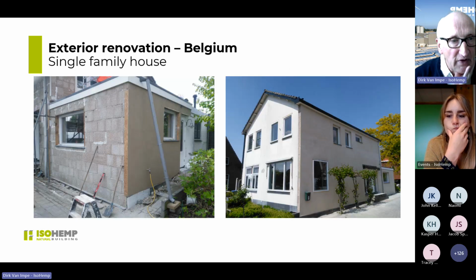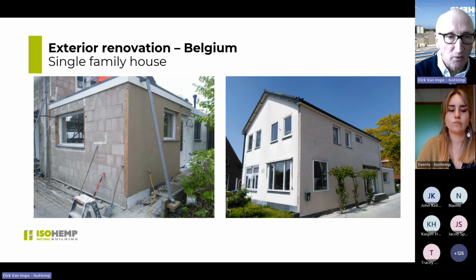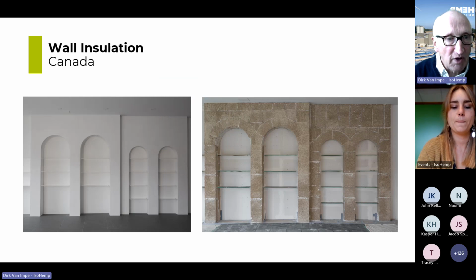And then you can renovate old buildings, also inside renovation. Nice pictures. You can also use the blocks at the outside. This is outside renovation. Then you don't make a shell of blocks at the inside, but you do it at the outside. It's also possible to maintain your old construction on temperature. Then it's the same system, masonry, always 15 or 20 centimeters above ground level, starting with the blocks, in between normal insulation, waterproof insulation, and plastering.